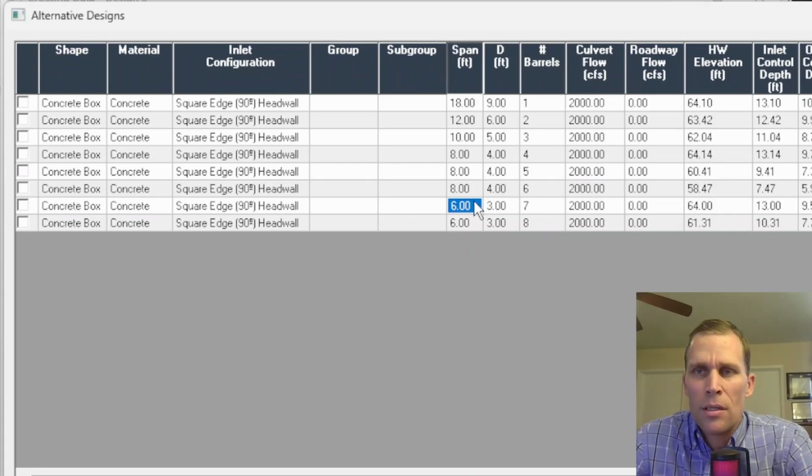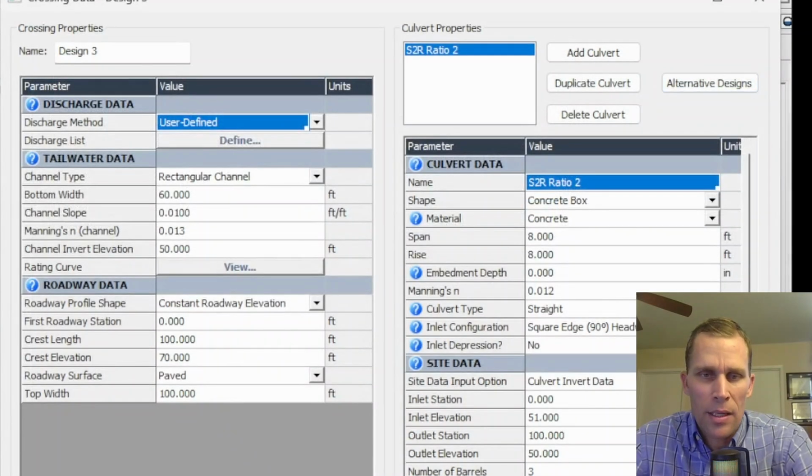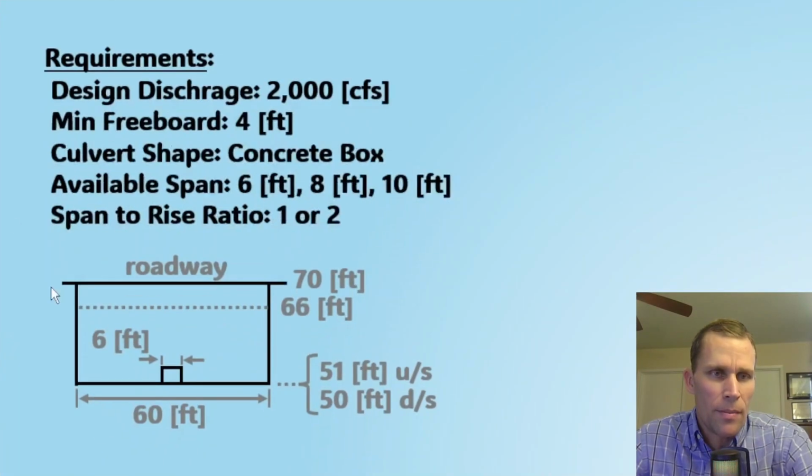Even when you consider the side wall of each culvert barrel is, like I said, 6 inches to a foot, you're still going to have enough room with our widest alternative right here. Okay, so just a good check to make. Otherwise, we may have to have a second layer of some of these culvert barrels, but we're good there. All right, so to summarize things, we go ahead and close that up and then bring up the PowerPoint.